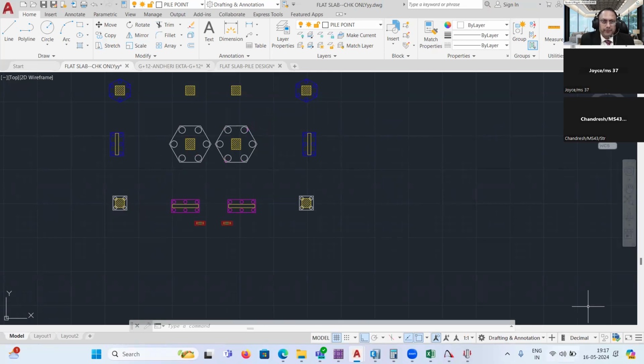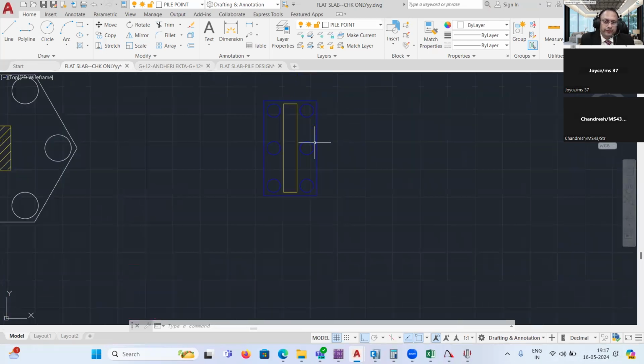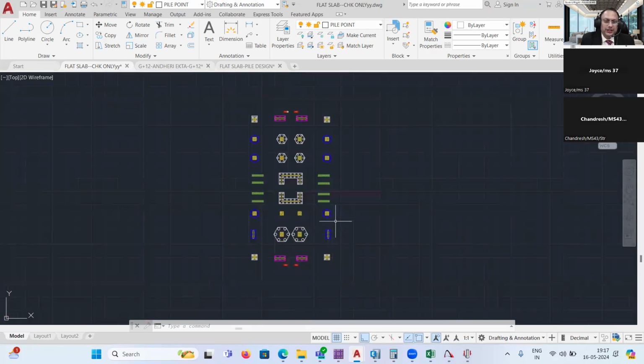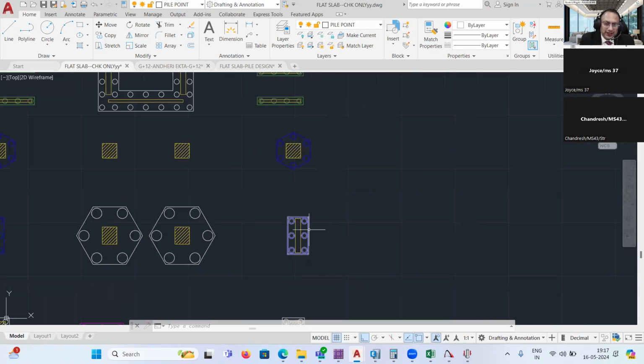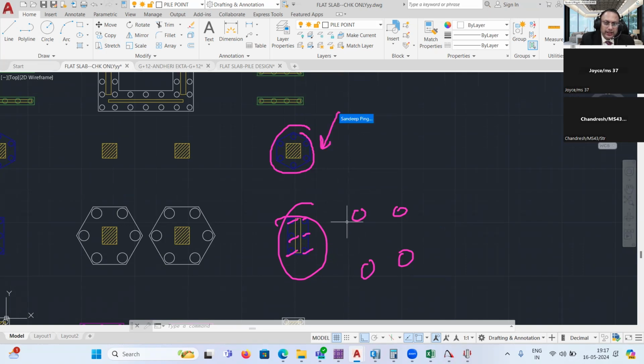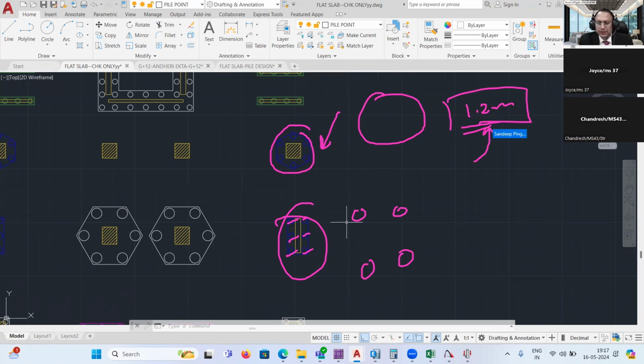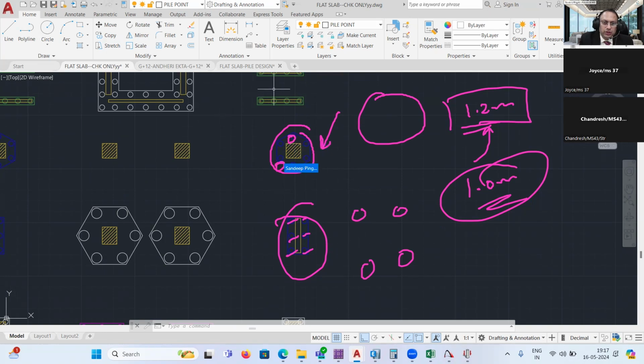Sir, and also this arrangement of pile for the shear wall here? That's what actually, it is good arrangement, but even though I would like to avoid this, instead of 6 piles. Try to give 4 piles. Try to give lesser numbers, higher diameter. You can go up to 1.2 meter. This is Mumbai. See, 1.2 is okay. I'm very much optimistic. You can at least go up to 1 meter, easily possible. So in the 1 meter, you might require maybe 3 piles. Matter is over.